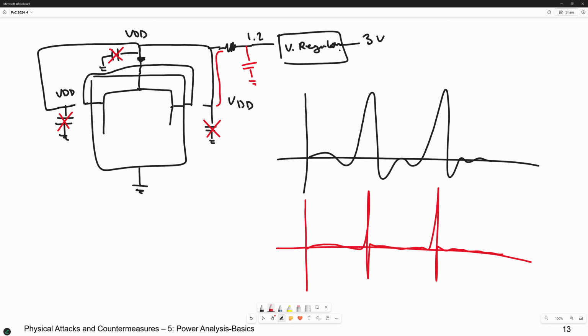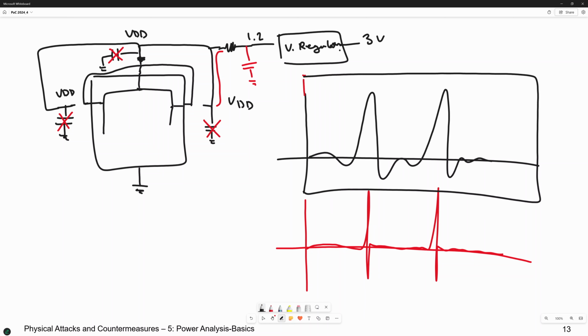For example, this is the full screen of your oscilloscope, and from here to here will be quantized. If you have an 8-bit ADC, then it will be quantized to 256 cases. If these are two different cases, something in between does not exist. This is quantization.